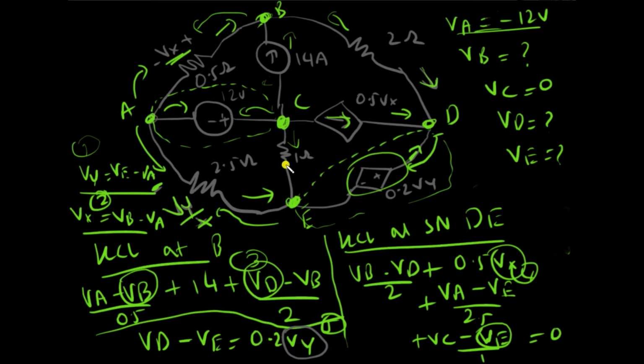So in a crux, what you need to know is that whenever you are applying nodal analysis and there are voltage sources involved, the first thing is to identify all the nodes, and then after choosing the reference node, start off by forming the supernodes. If your supernode consists of the reference node, like in this case, you just write a simple equation and no KCL for that. For the other supernodes that do not have the reference node, you do write a KCL, but the KCL combines both nodes and does not include the branch of the voltage source. So this is what you omit from that KCL. You just combine the KCL of the 2 nodes in the supernode if they are not the reference node. So these are the 2 things.